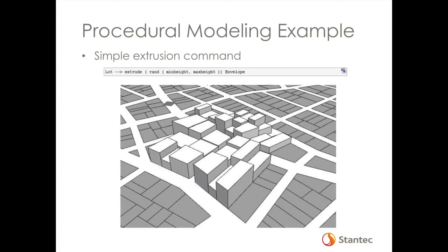So very simple line of code, but basically with this data set you can select thousands of polygons you've got in this GIS data set, and it'll automatically extrude shapes to different heights. You can also read attribute data from GIS, so if you had a data set with footprints and heights, you can read that data set, apply the rule, and it'll actually recreate buildings within a box look, but it'll actually recreate a building based on a rule.